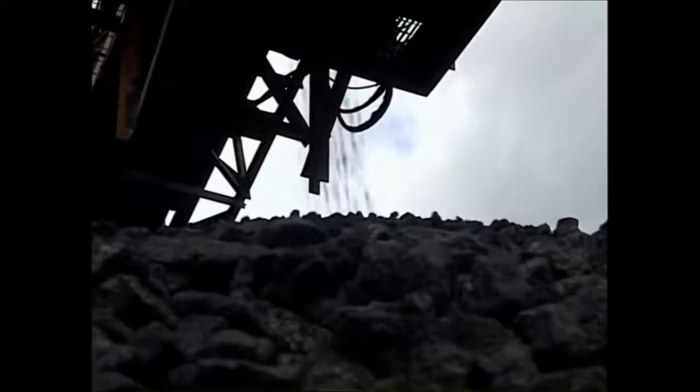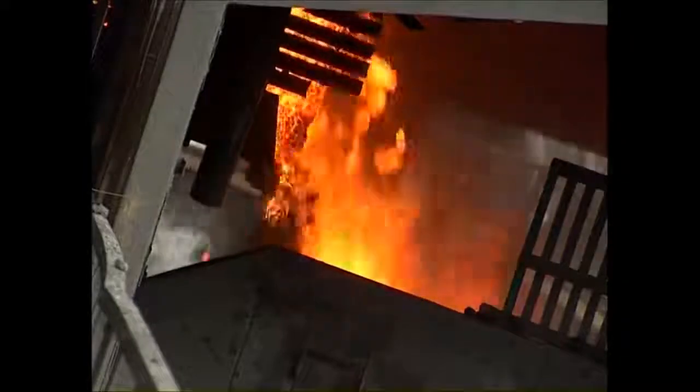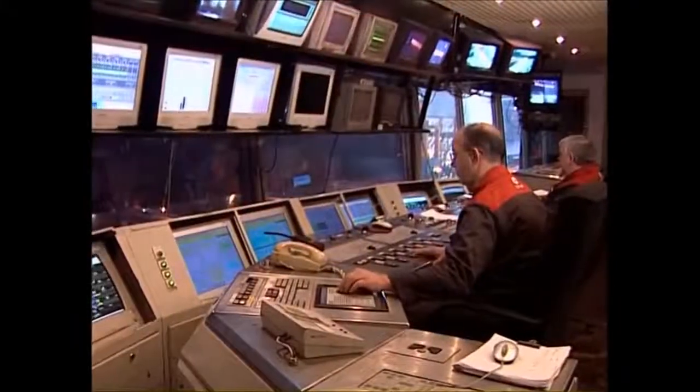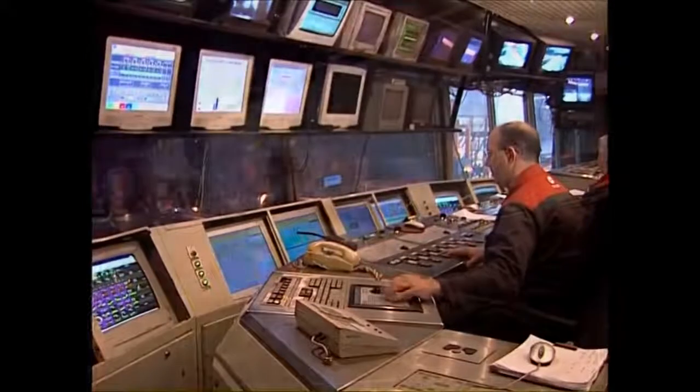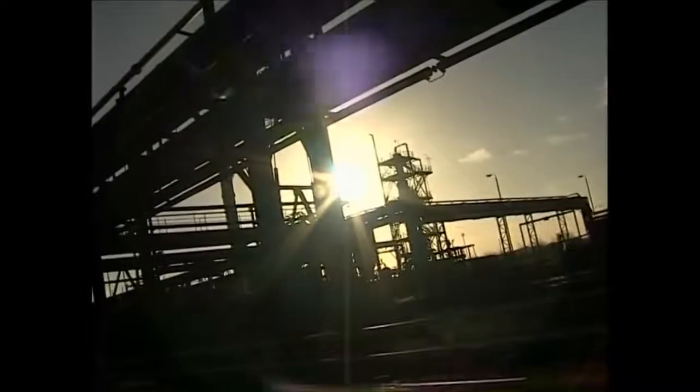Carbon is required for the blast furnace, and this is supplied in the form of coke. To make coke, coking coal is heated in an oven. This drives off volatile byproducts and leaves carbon. Gas produced in this process is used as a fuel, whilst other byproducts such as tar and sulphur are extracted and refined.